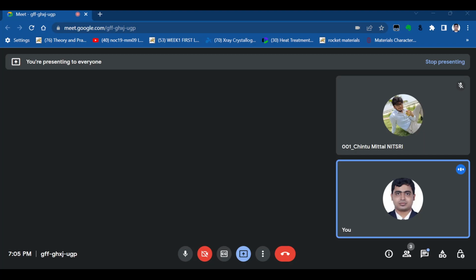Wherever the circle cuts this x-axis, or sigma axis, this is your sigma 1 or sigma max, the first principal stress, because here the tau xy is 0. Wherever tau xy is 0, that is your principal stress. This is sigma 1 and this one is sigma 2 or sigma minimum. And the value of this radius is your tau max, the maximum shear stress.